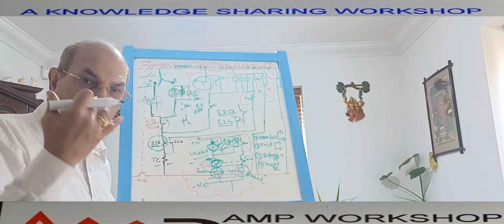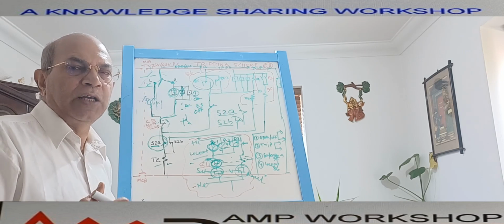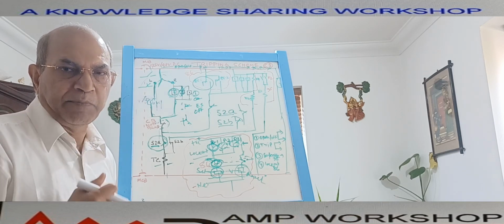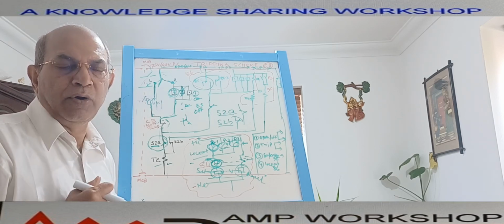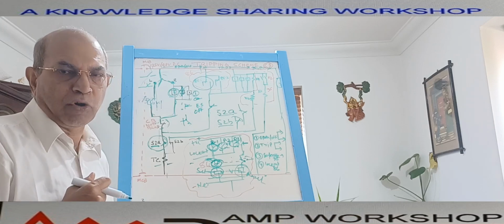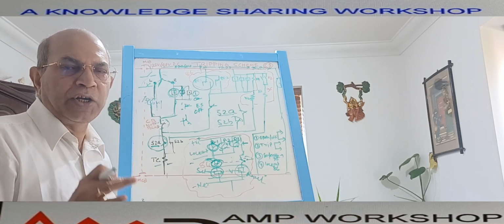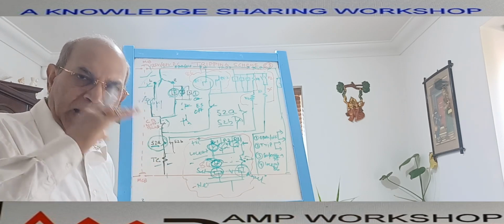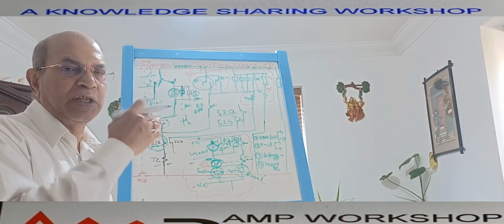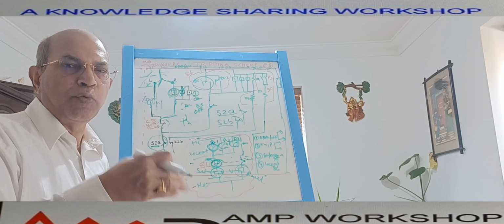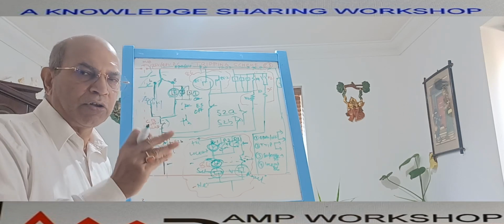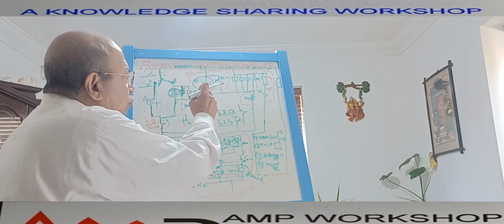Then maybe there is another lockout relay, which is sensing the transformer's other minor faults, like transformer over temperature, transformer liquid level low, or the pressure relief device operated. This type of minor condition we generally group in another relay. Or maybe, due to breaker failure of another breaker, this breaker needs to trip. That we may group in an undervoltage trip, put in another lockout relay. This way we can use multiple lockout relays. I have shown here two lockout relays.